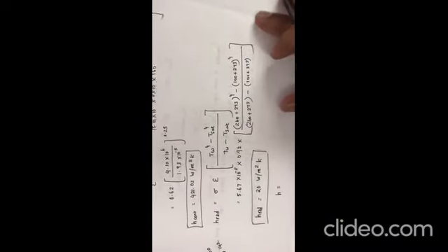Now H, the overall heat transfer coefficient, will become H convection plus 0.75 of H radiation. So this will be 421.02 plus 0.75 into 20. So the overall heat transfer coefficient will be 436.02 watt per meter square Kelvin.